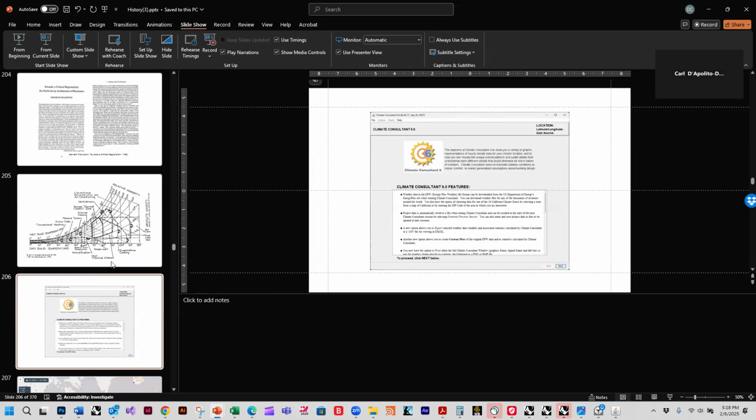So I think what's important is just two things. One is to understand how hot it is, the dry bulb, and how cool it could be with water, the wet bulb. And you can plot those things monthly, and you get that interesting diagram that can tell you whether or not it's nice to be there at that time. You can plot it with Climate Studio. I don't know if you guys know how to plot it. I'll show you. But you can plot it with Climate Studio, you can plot it with anything.